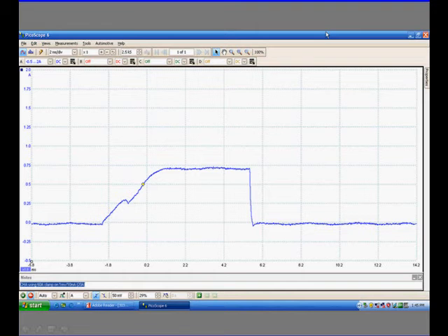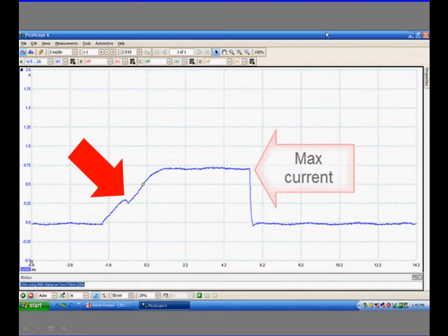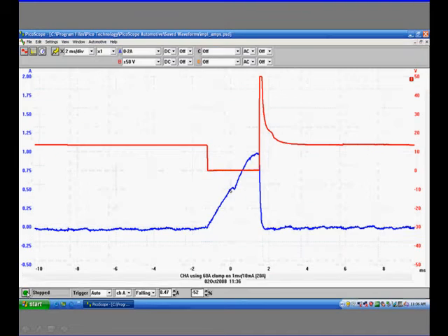Here is an injector current waveform. You can measure with your cursors the current being drawn by the injector. And don't forget, you should see some type of pintle hump. Now this is an excellent pintle hump on this waveform. All injectors don't have a pintle hump that is that obvious. Sometimes it's very difficult to see, but just make sure it's there.